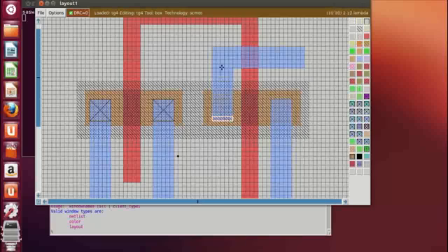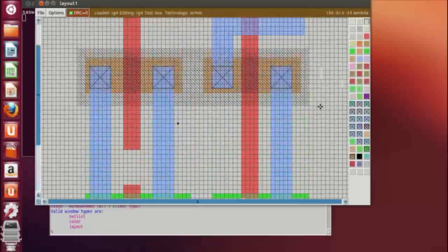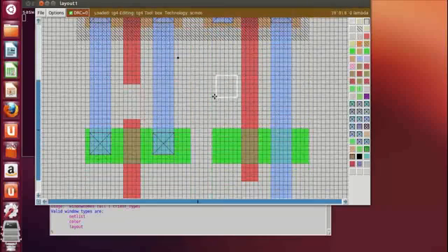I want to extend it by a metal layer. I want uniformity in my layout. So that's the reason why I keep on extending. Now the PD contact. This is also my PD contact. So we had there PDC, here it is the PD contact, and here the NDC, N diffusion contact. Yes, this is our VDD, so we have not taken the ground.